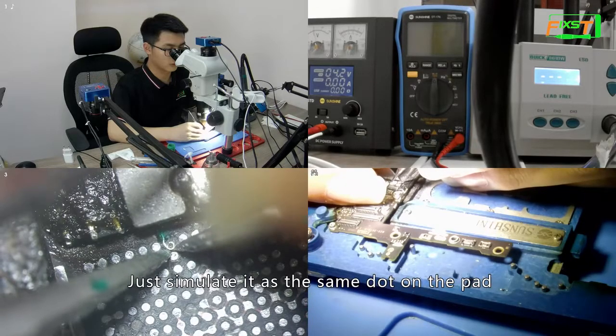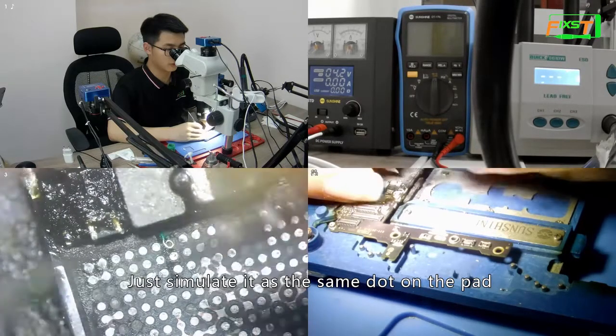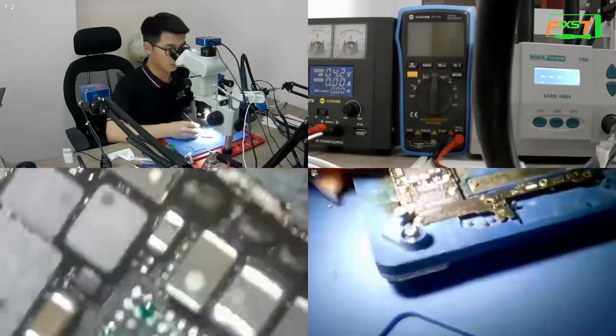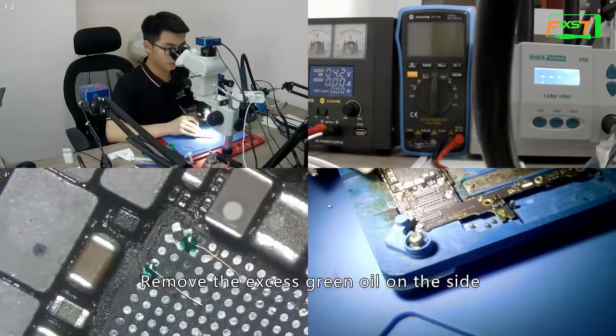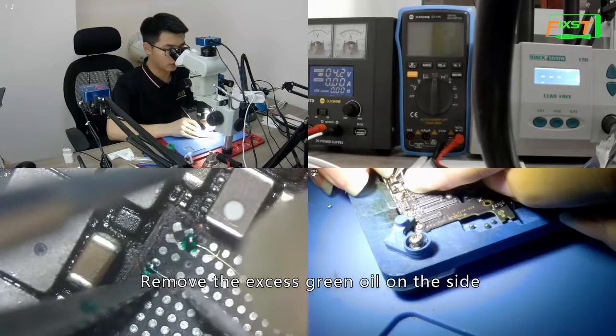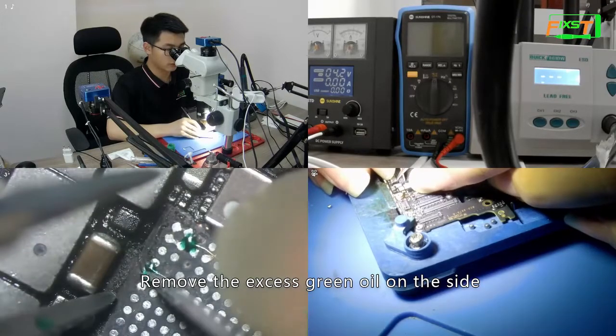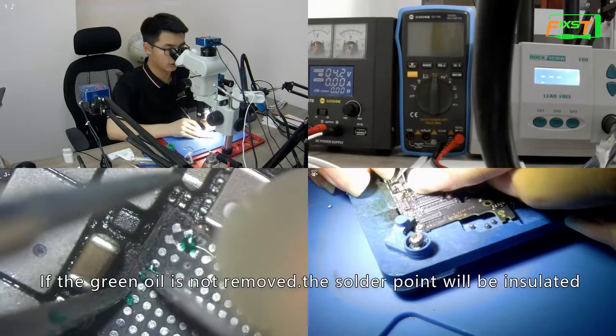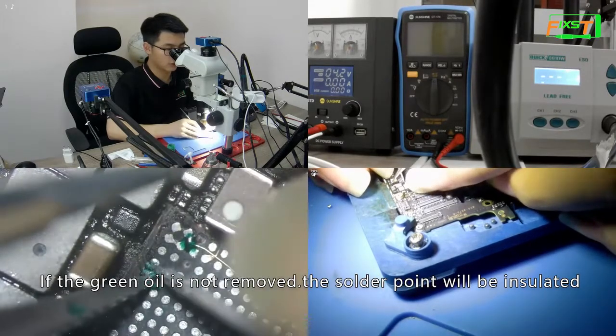Just simulate it as the same dot on the pad. Remove the excess green oil on the side. If the green oil is not removed, the solder point will be insulated.